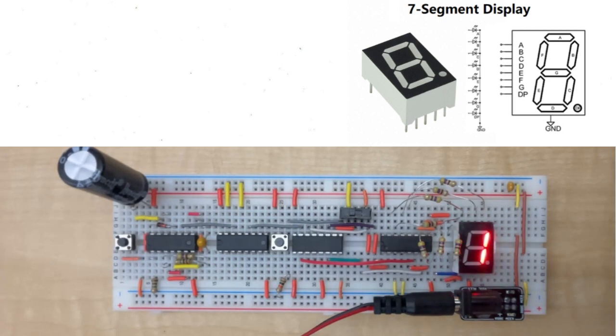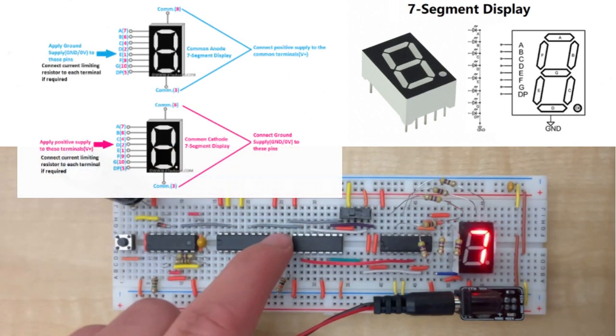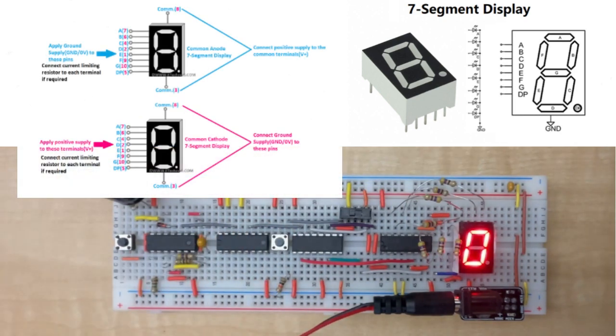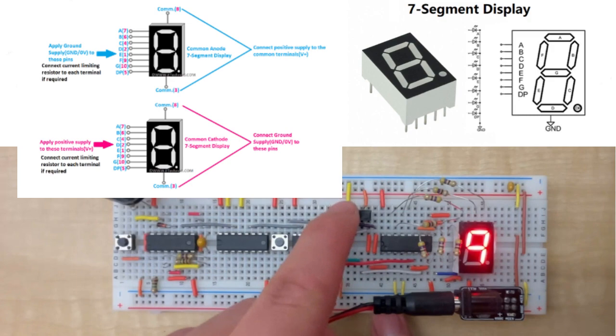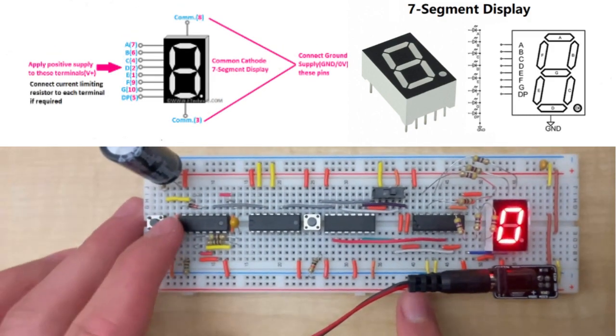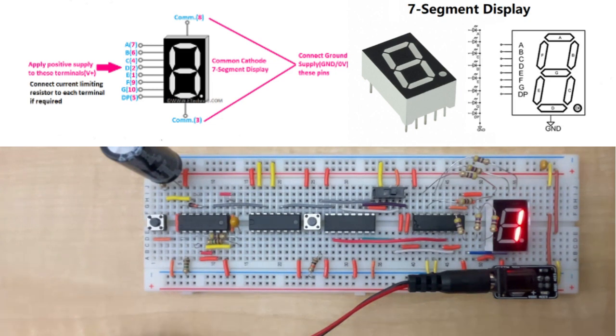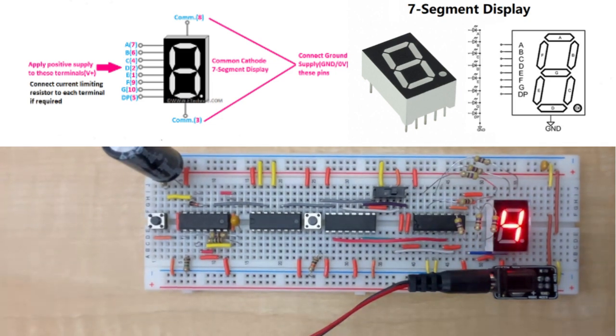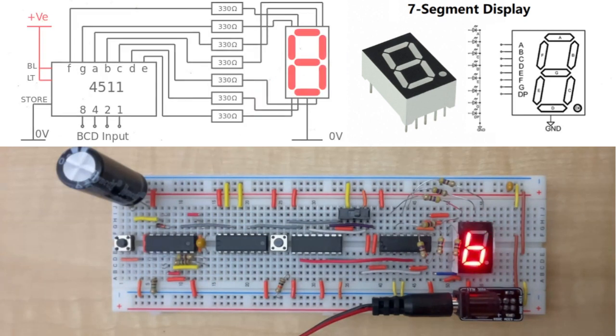The 7-segment display is used for visualizing numbers, comprising 7 LEDs arranged in a digit pattern. There are 2 variants, common anode and common cathode, differing in their internal wiring arrangements. A common cathode display connects all cathodes together, while each anode is controlled individually, contrasting with the common anode displays, which are the opposite. Our circuit used the common cathode display. To protect the LEDs and chips, each pin requires a resistor to regulate current, preventing excessive current that could harm parts of the circuit.